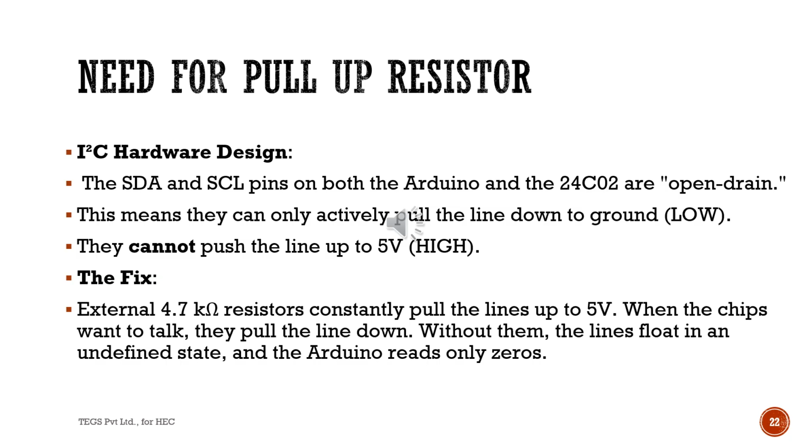When the chip wants to talk, it will pull the line down. Without the resistors, the lines float in an undefined state, and the Arduino reads them as 0. This will lead to errors in reading and writing.